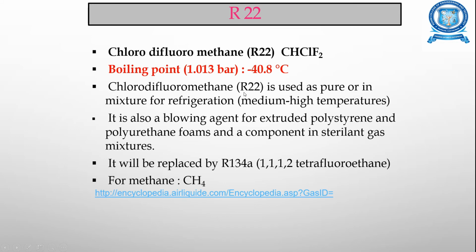The boiling point is minus 40.8 degrees Celsius. Chlorodifluoromethane R22 is used pure or in a mixture as a refrigerant at medium high temperatures. It is also a blowing agent for extruded polystyrene and polyurethane foams, and it is a component in sterilant gas mixtures.